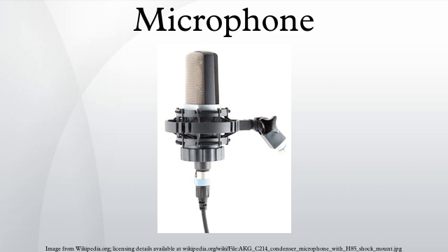For large membrane microphones, such as in the octaver, the upward direction in the polar diagram is usually perpendicular to the microphone body, commonly known as side fire, or side address. For small diaphragm microphones, such as the Shure, it usually extends from the axis of the microphone, commonly known as end-fire, or top-end address. Some microphone designs combine several principles in creating the desired polar pattern. This ranges from shielding by the housing itself to electronically combining dual membranes.